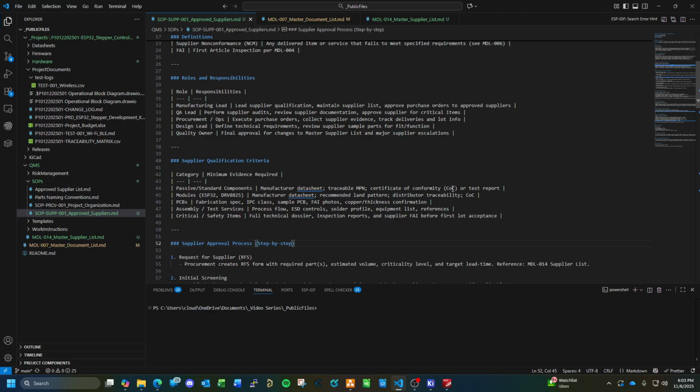We ordered a couple additional sensors from a different vendor like DigiKey, built up a couple additional boards, and they acted differently than the development kit. We put them under the microscope and checked the markings on the chip, and sure enough, the chips on the Amazon low-cost dev kits had different markings than the official ones from Analog Devices.